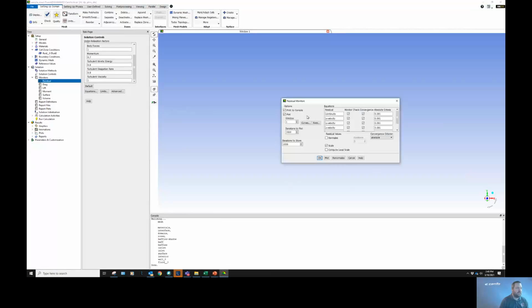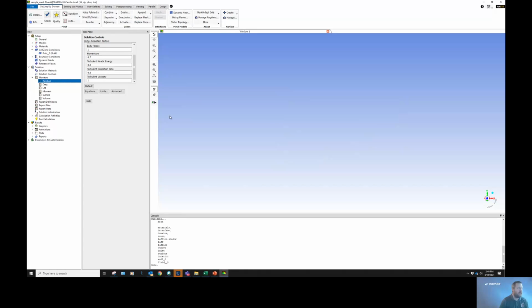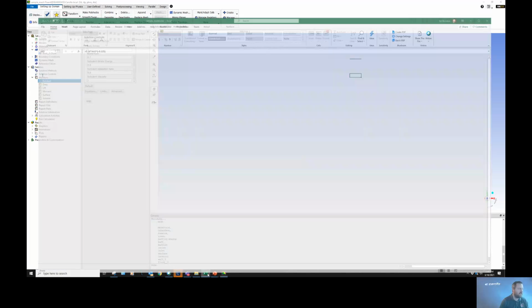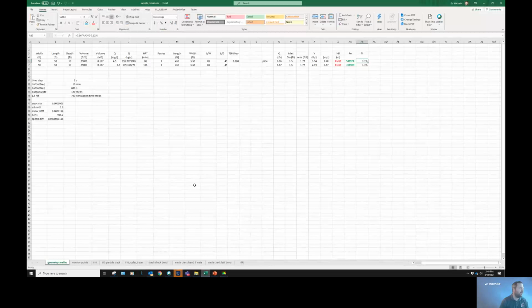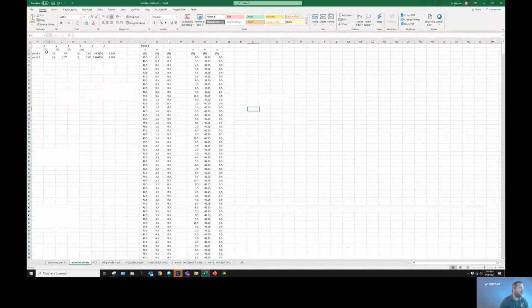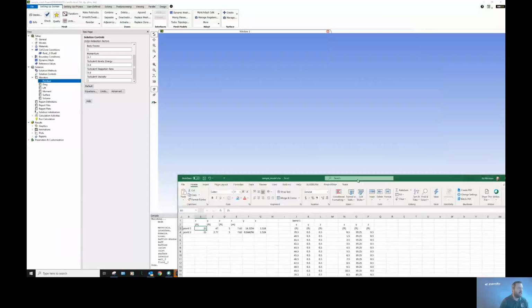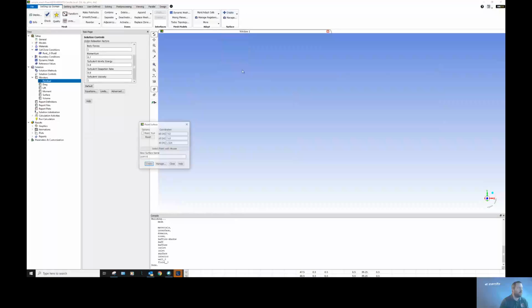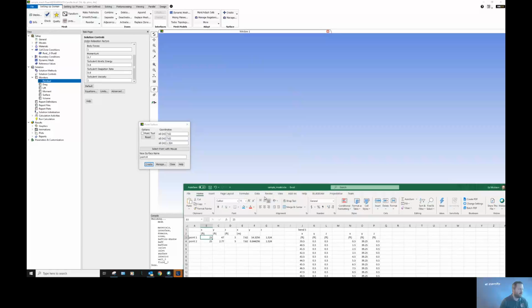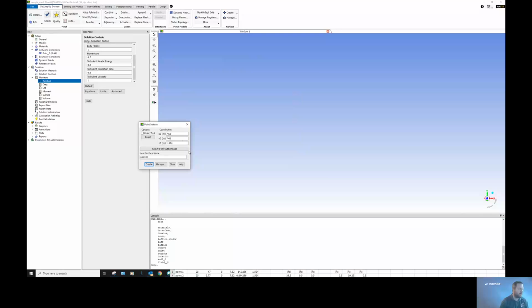So we've got an absolute criteria of 0.001 for everything for now. And we'd also like to define some point monitors at areas of interest. And so we would set up our points here. These are in wake regions at some of the bends that we've pre-estimated as areas of interest. And so for XYZ coordinates, we create a point at these locations.